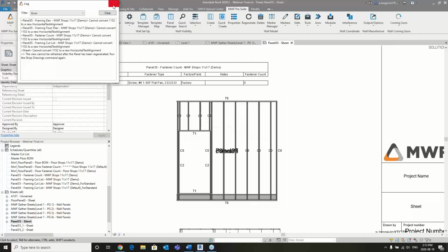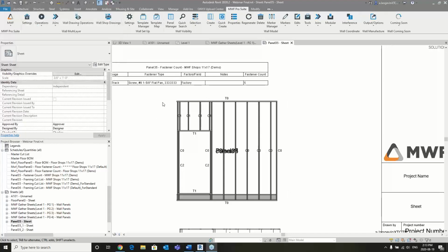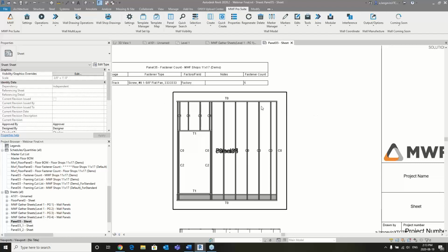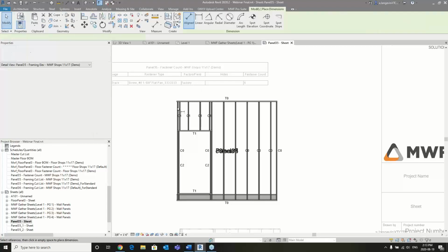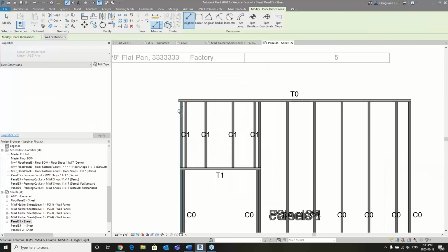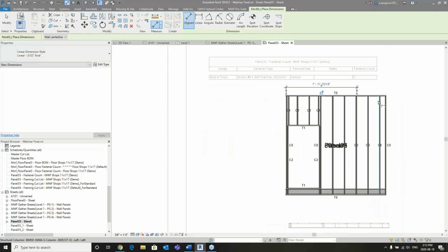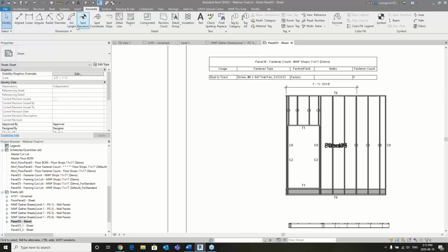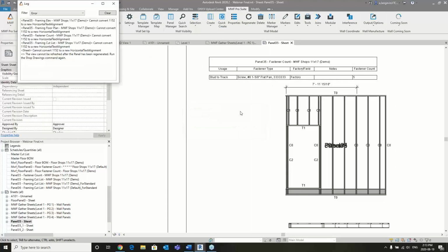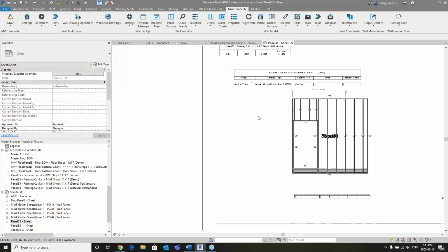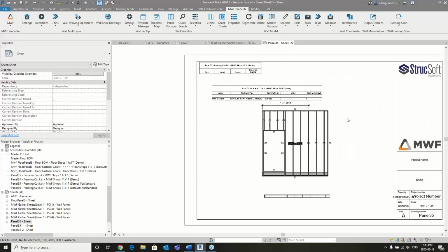Refresh my drawing. Okay, so you can manually add some annotations, and they're not going to disappear if you have to refresh the drawing. So as you just saw before, I can come here to annotate. Just pick from here to here. Okay. And when I refresh my drawings, these annotations should stay. Okay. So that's another little addition we did for shop drawings. Next.